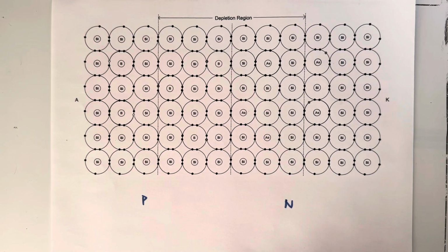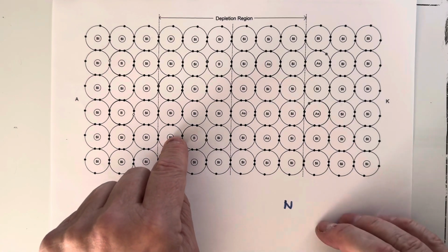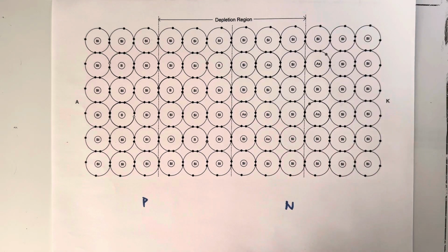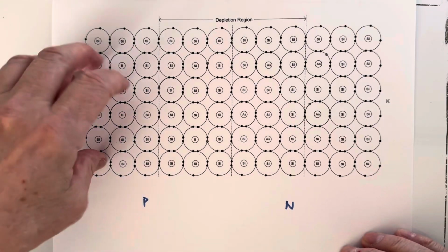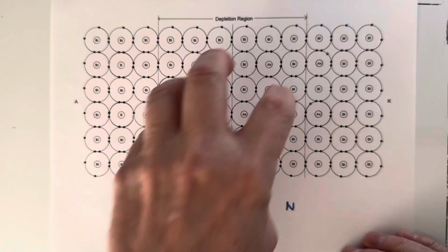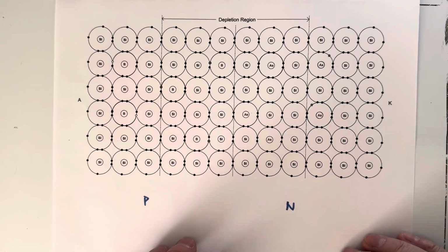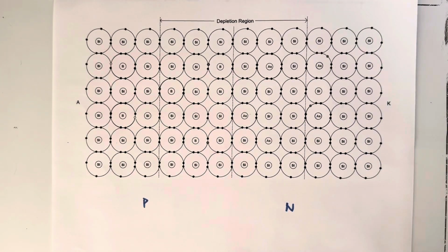in the N-type region. This is called a depletion region because everywhere that an electron has recombined with a hole, there are no longer any free charge carriers available. So, while the intrinsic silicon is a terrible conductor, but P-type silicon and N-type silicon are good conductors, the depletion region has no charge carriers, so it acts as an insulator between the P and N regions of the device.